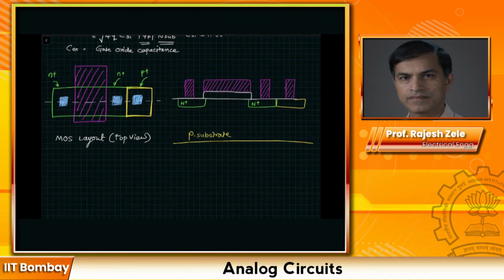If you remember the first lecture in which I showed you a silicon wafer, that's what we call a P type substrate. We start off with a P type silicon wafer, and then we start doing the doping in that silicon wafer. The yellow region here is P plus doping, and the magenta region is showing the metallization. The white region is actually oxide.